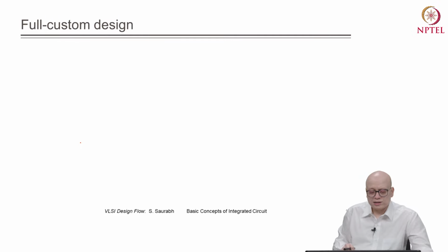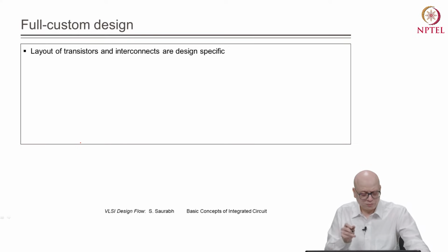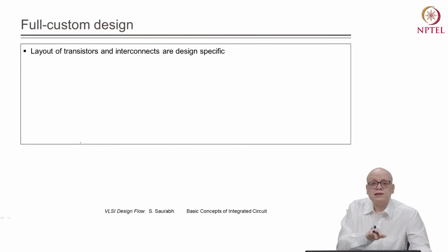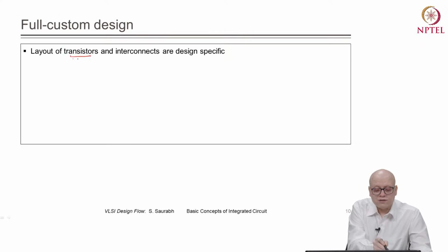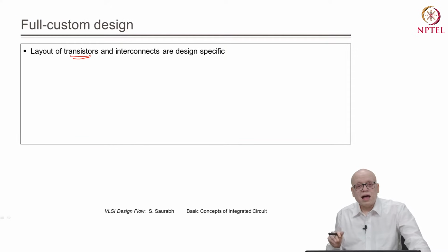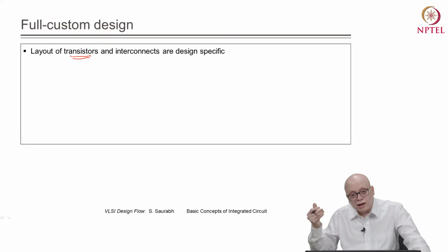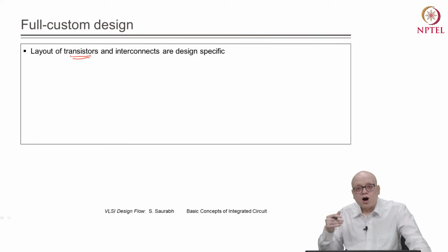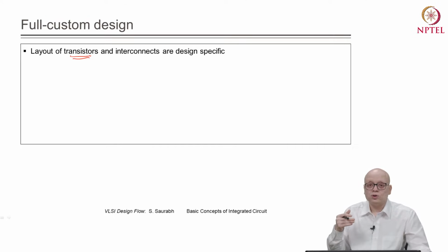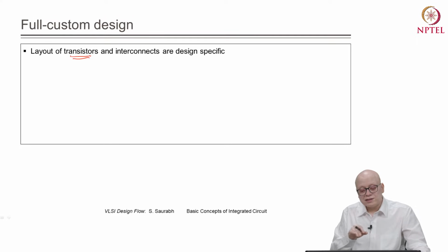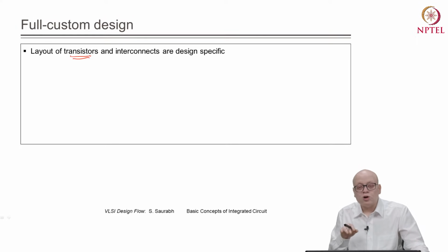Now what is a full custom design? In full custom design, we design the circuit at the transistor level, at the lowest level, right? And we decide the layout of the transistors, the geometric aspects like W by L of the transistors, and how those transistors are connected and so on, right?